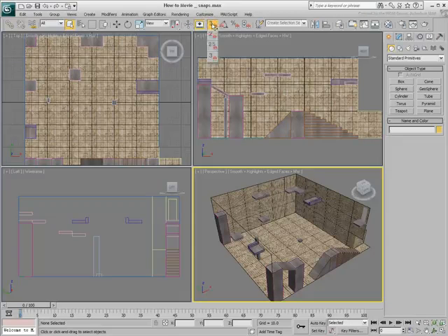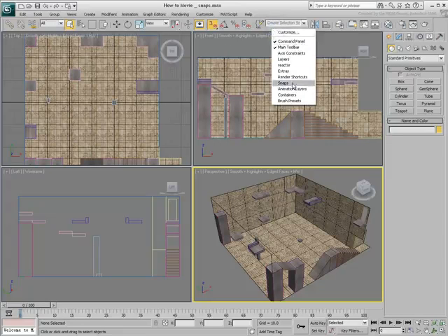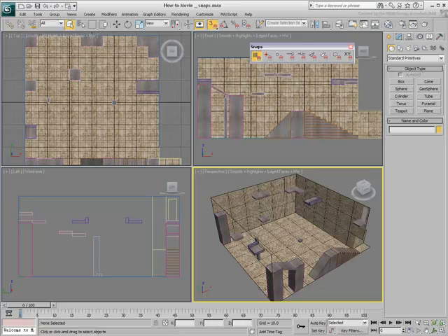The Move Snap tool is actually a flyout. You will learn about its various options in a moment. For now, leave the default 3D snap mode active. When planning to use snap tools, it is usually more efficient to call up the Snaps toolbar. This can be done with a right-click on an empty area of the main toolbar.